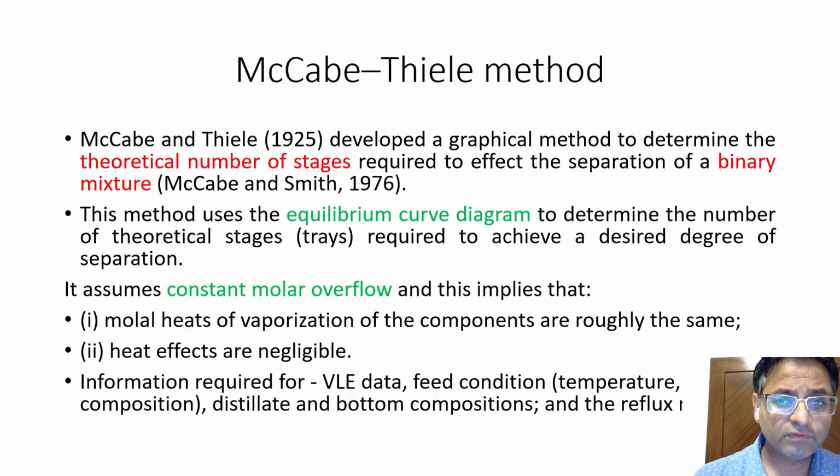So what information do we require for this method? We require the VLE data, feed composition, temperature, distillate and bottom composition, and the reflux ratio.